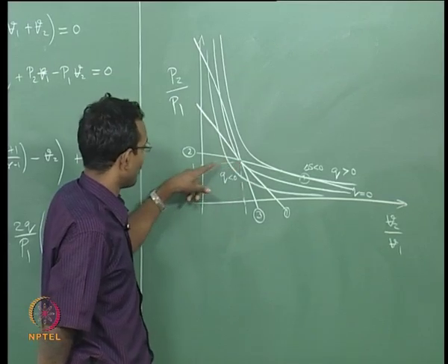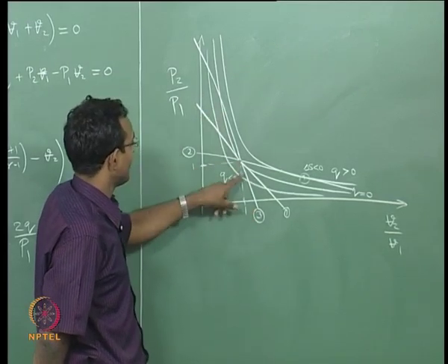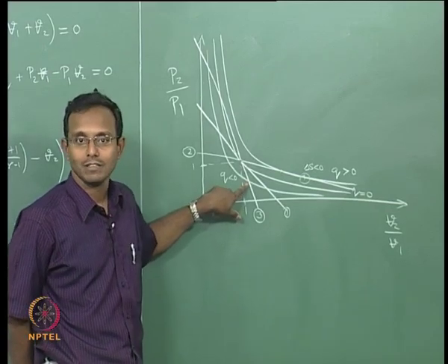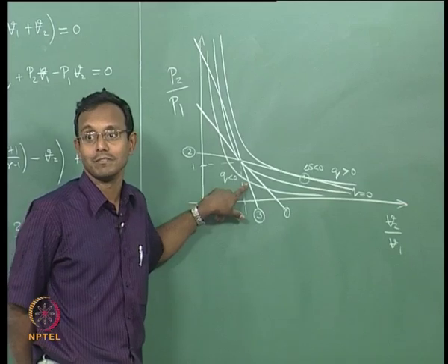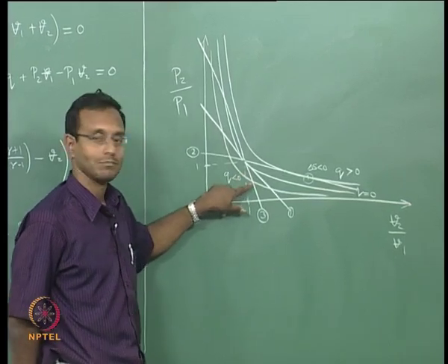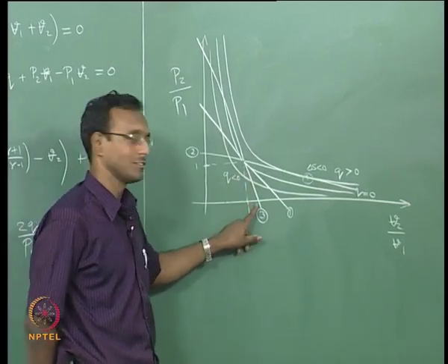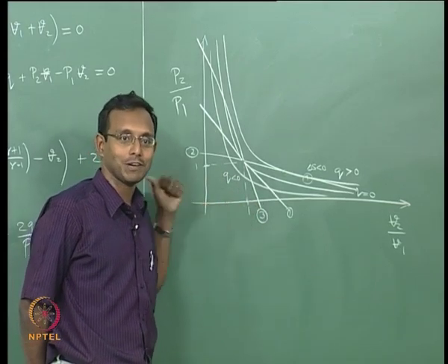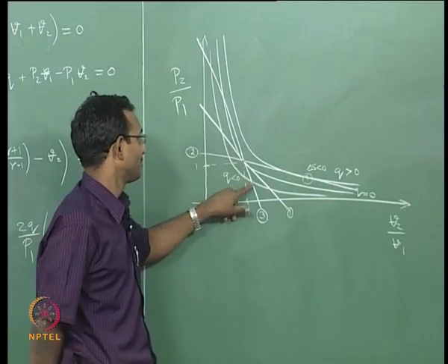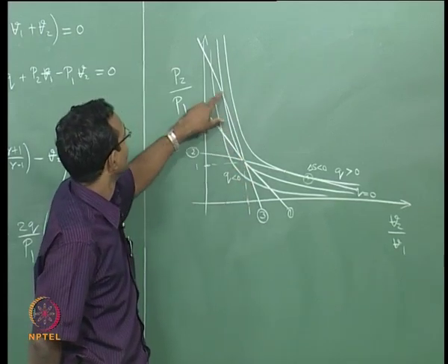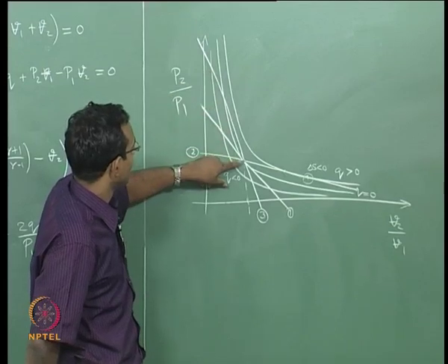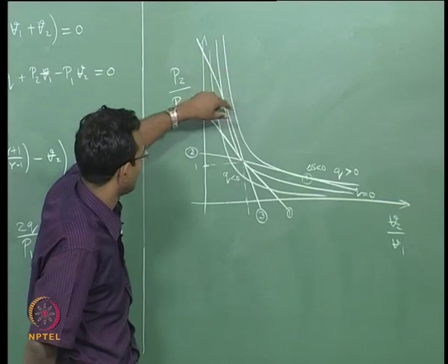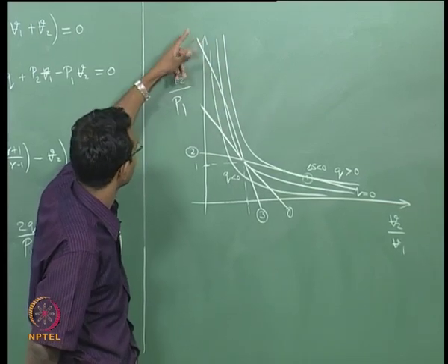And if I go to high Mach number case, if I cool the gas, I am going to get lower pressure, that is I am going to even higher Mach number, that is this solution. And you can see that the volume increases, that means my density dropped. I am expanding further to higher Mach number, that is this particular solution. When I go the other side, this particular line, if I go from here and heat it, oh I drew the Q such that it never touched it.